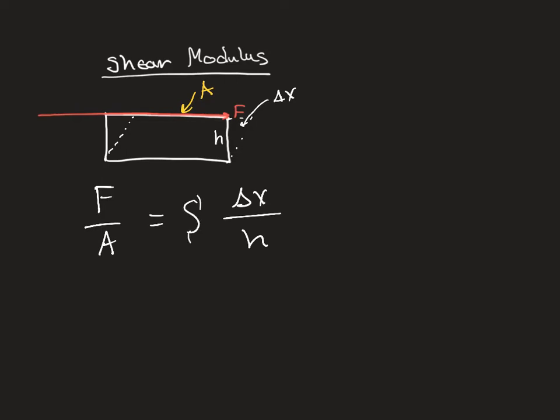And our proportionality constant, as already hinted by the title, is the shear modulus. Also, it's going to have units of pascals. And the shear modulus is different than the Young's modulus, and once again, it's also different for each material that you might be applying a force across.